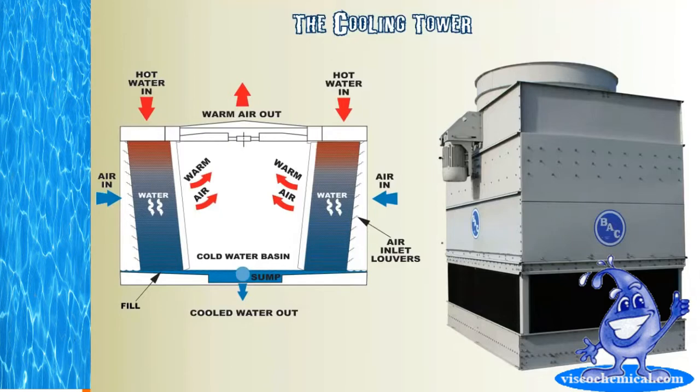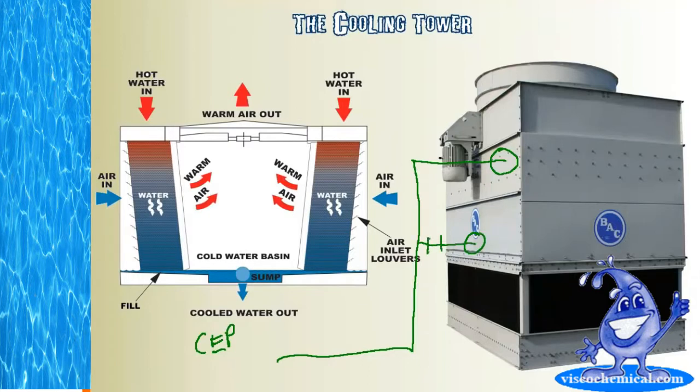One other thing you can have for cooling towers is a bypass. What a bypass valve does is normally that hot water comes in here at the top, and let's say it's coming from the central plant. This will be the central plant over here. But instead of going through the top here, they'll tap in another pipe right here. And they'll put a valve here and a valve here. Sorry, my drawing skills are lacking right now. And these two valves will be linked together with one actuator.